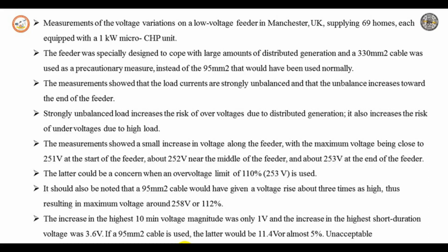The cross section of the 3 phase feeder, that is 3.1 kilometers, is 120 mm square, the single phase feeder, that is 2.3 kilometers, has a 70 mm cross section, and another cable with 50 mm square has been considered. These networks supply 307 low voltage customers. You can imagine, in only 3.1 kilometers this network supplies 307 low voltage customers.